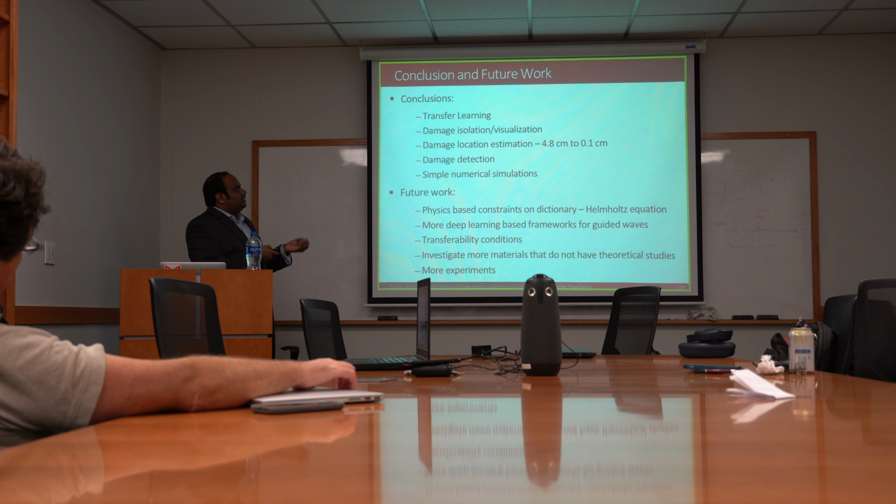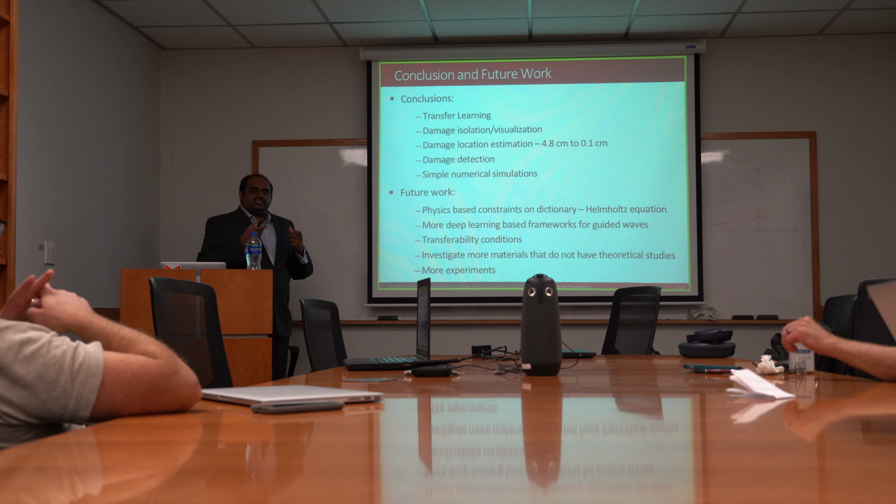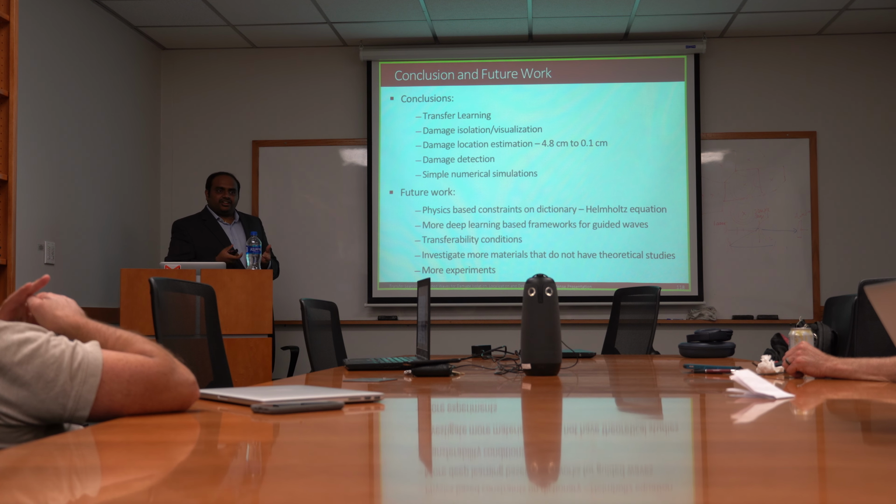I decreased the error from 4.8 centimeter on a 10 by 10 plate to 0.1 centimeter. And then I did damage detection as well on these plates. And then instead of assuming experimental data from a surrogate structure, I used simple numerical simulations to do the subtraction, to learn from it.